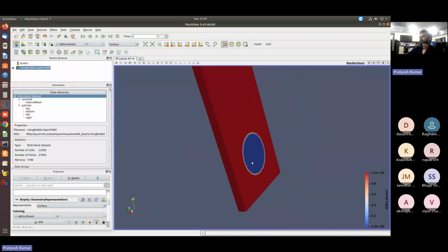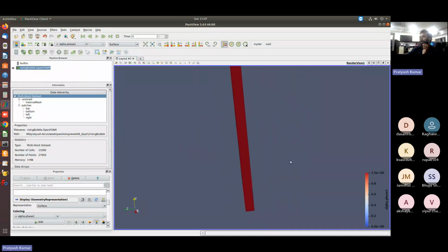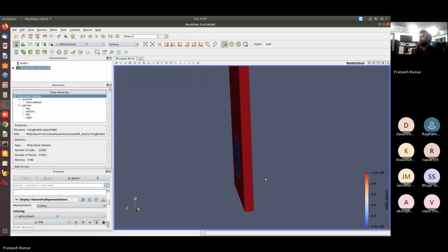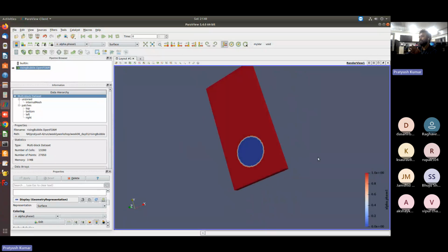But within this cylinder, so that is one kind of cylinder that you can see, within this cylinder the value is going to be equal to 0. Okay, so this is how you can select the number of cells within the given cylinder. If you have some 3D condition and there you want to select the cells within the given sphere, then you can use this kind of utility.